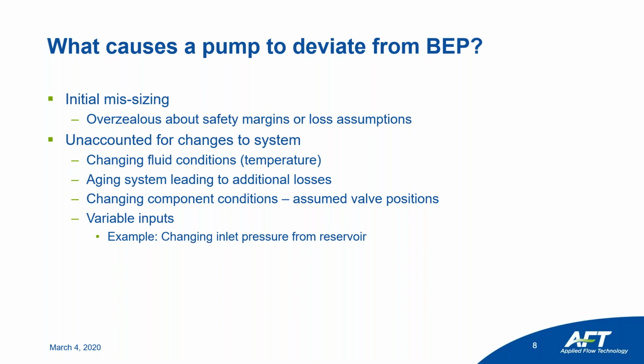And so, especially with some valves, based on the characteristic curve, what you think is 50% may actually be 60%. And so that can cause difficulties, and that can also run into problems if, again, you're running into these assumptions.